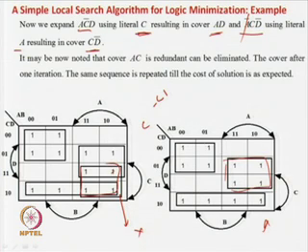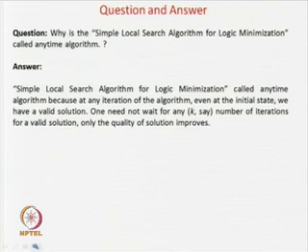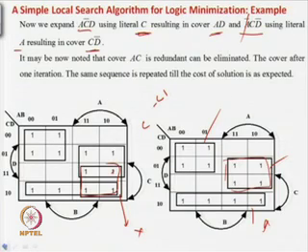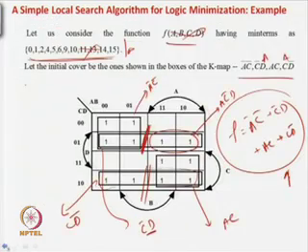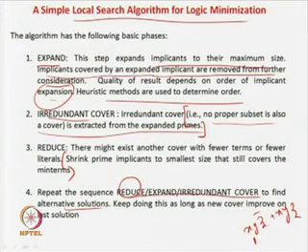So you can eliminate this, and now you can have this, this, and this, and you have got a minimized result. Okay, so that is what Espresso is. Let me again reiterate what I have done. What is the first case? The first case is reduce. What do you mean by reduce? Reduce means there might exist another cover with fewer literals.